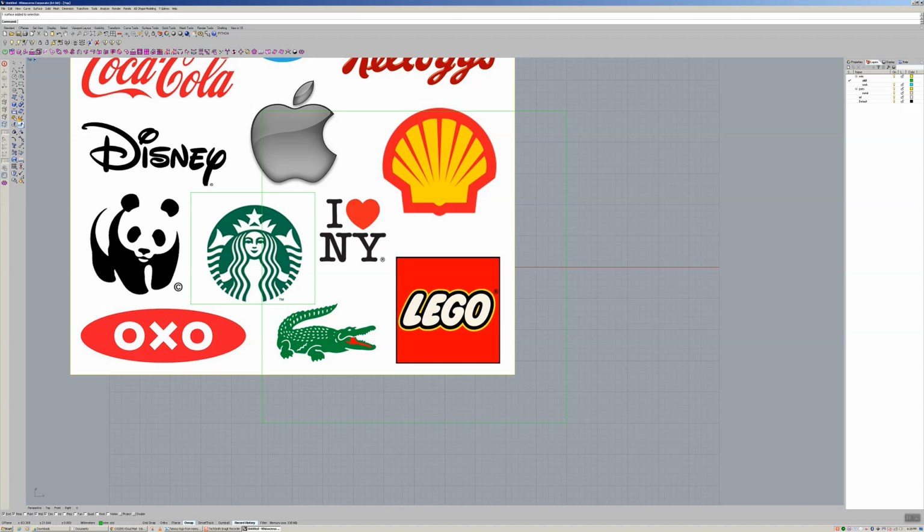Okay. All right. So I'm clicking on it, and now it's asking me for the cutter. The cutter is the box that we made around the design. Let me know when you guys are ready. Okay, watch. Take a look. I'm gonna click, and now I selected the cutter, and you can select more than one cutter. So say there was another cutter, I could select that one, but we only needed that one cutter. So now to end the command, you either hit return or enter, or right click. Right click is enter. It does the same thing as enter. So let's hit enter, okay? And now we cut it.